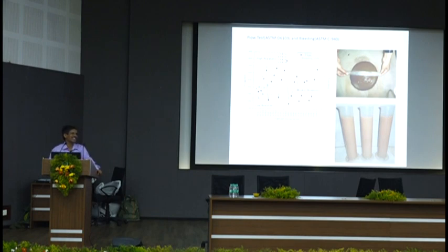We use a hydrometer jar, a cylindrical jar, and at the top we check whether any water is there. That means they are segregating. That is what we call bleeding. Based on that we have plotted, and depending upon the flow value, it is high flowable, medium flowable or low flowable. Accordingly, you can use it where you want.